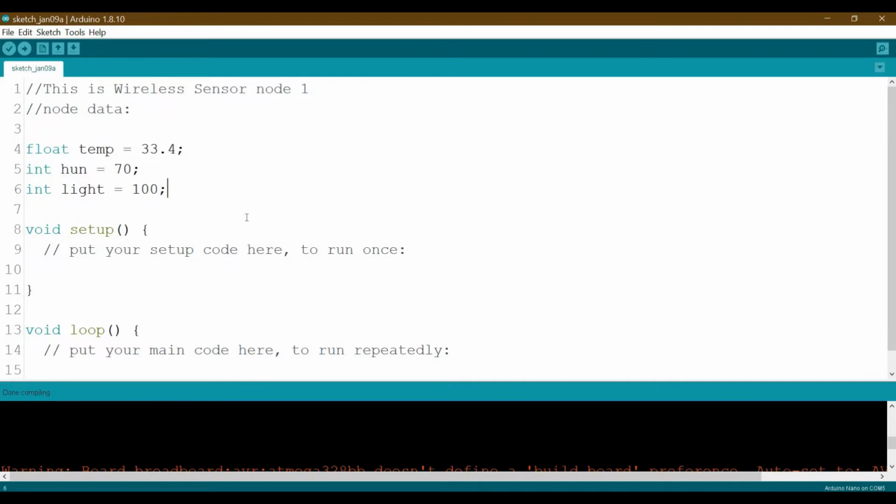So this is the data, and we want to send it to another sensor node on the same network. For sure, we're going to use RF, and we will assume that the RF module uses serial. Actually, we can use any other peripheral, let's say I2C, SPI, whatever. But here, just to show the concept, I'm going to use serial.